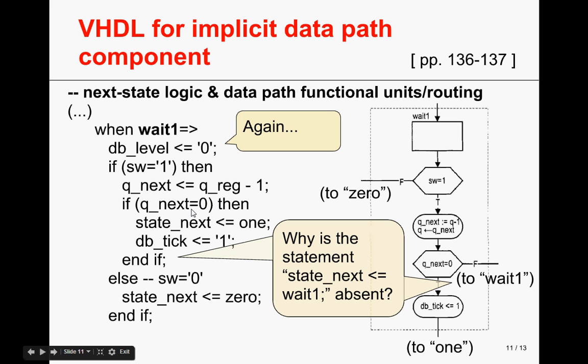Now at this point I would like to tell you that you might also consider, instead of using Qnext for this decision box, which is the one that we are looking at here now, we might have used Q_reg. And in this case, of course, we would ask if Q_reg is equal to 1, because that could correspond to Q_next being 0.